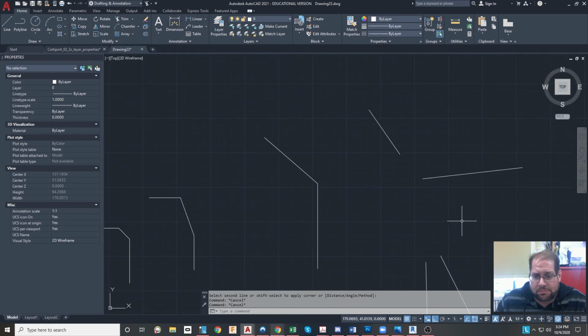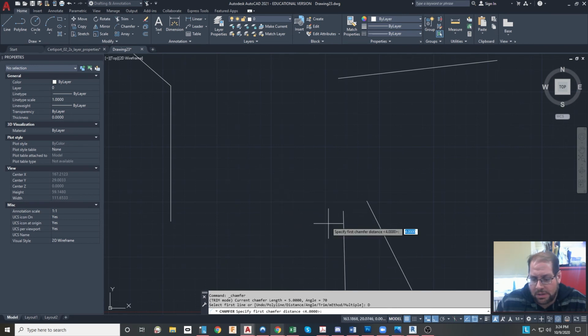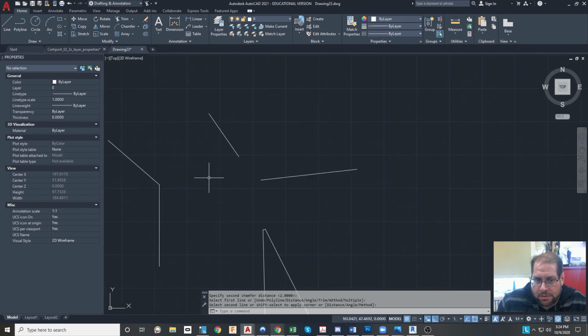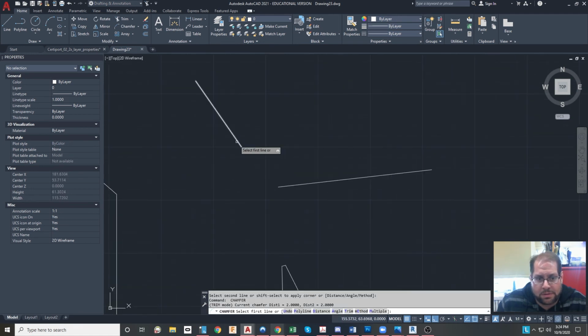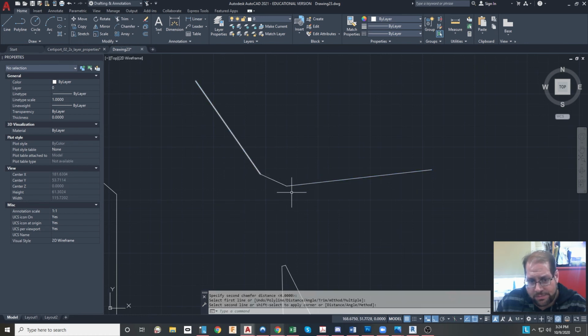And the chamfer also occurs very nicely with these things over here. It's a little bit weird, but you can get the idea. If I do distance chamfering with these two lines, I'll set it to just be 2 for both. It'll change the lines accordingly to make them match with a chamfer distance of just a 2 over there. And I'll try that again over here as well. This time I'll set the distance to 4. Okay, so the lines are modified, both of them. One is shortened, one is lengthened, and that has a chamfer distance of 4.